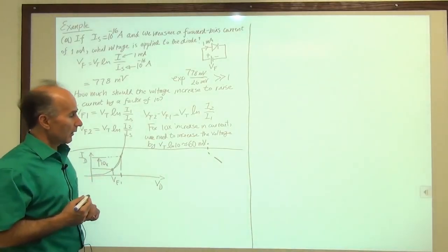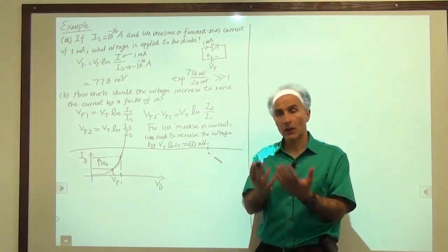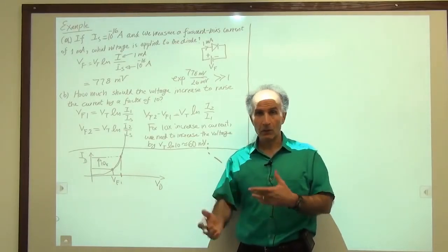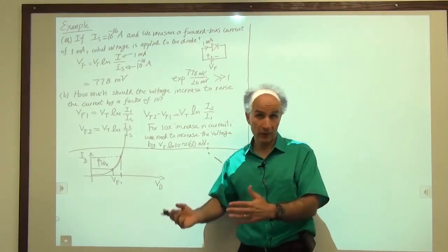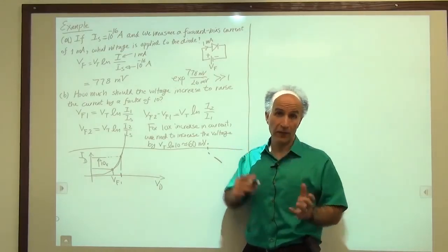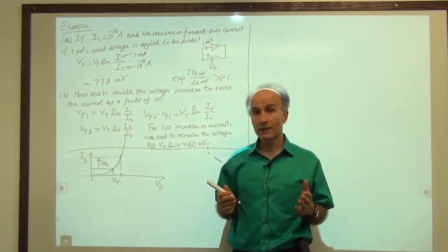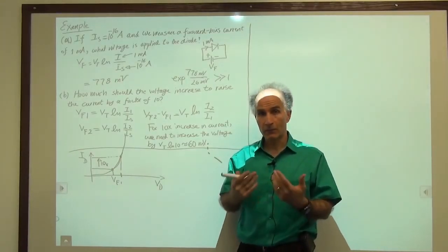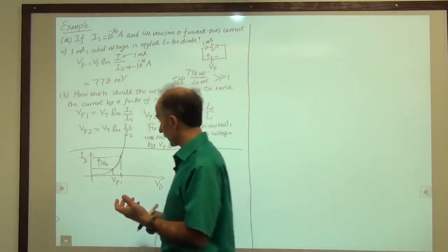Okay. All right. So this also tells us something else. If the currents that I use in practice in my field are all on the order of 1 milliamp, 2 milliamps, 3, 4, 5 milliamps, maybe 10 milliamps, in that range, I am not dealing with very high currents or very low currents, then I can say that the voltages that I will observe across forward bias diodes in my field are approximately what we calculated before.